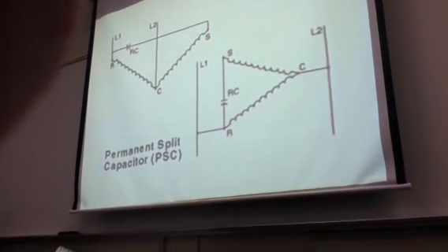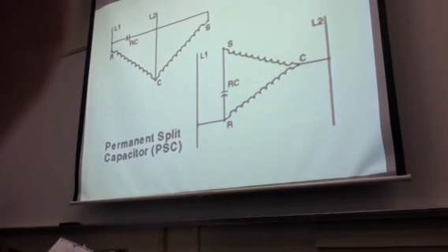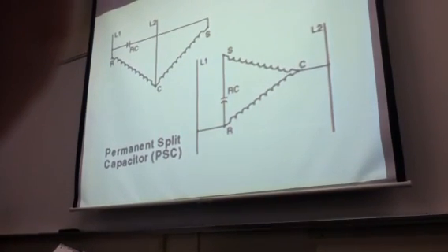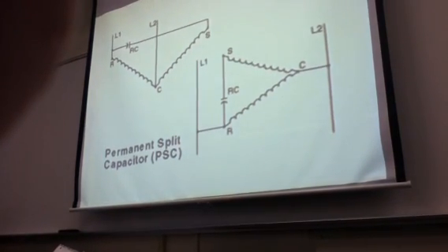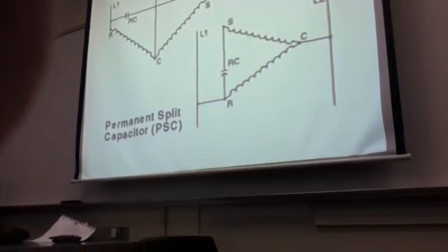The run capacitor has a relatively small MFD rating to limit current through the start winding. The low MFD rating also results in a small phase angle change, which explains why there is only a moderate starting torque.